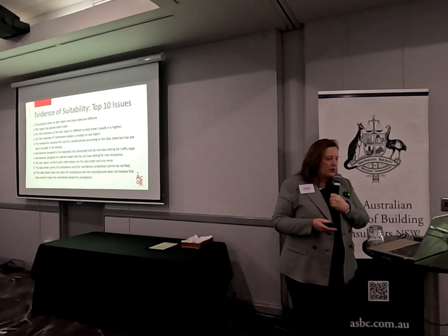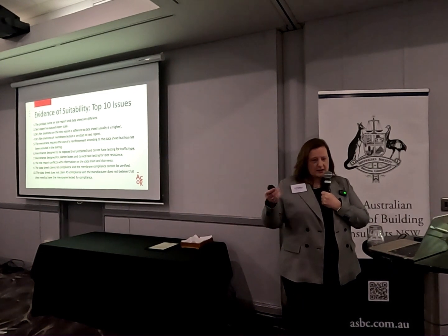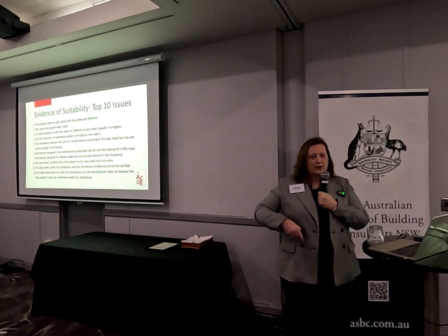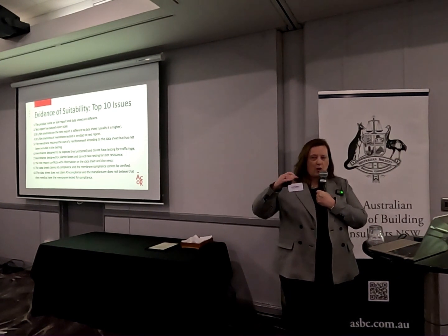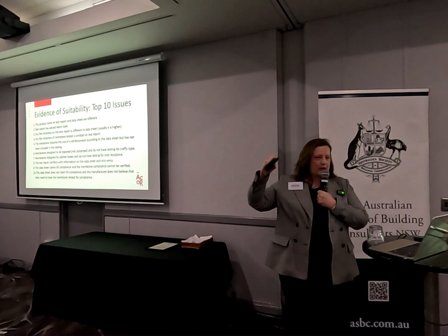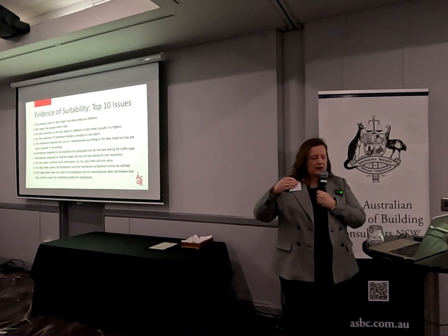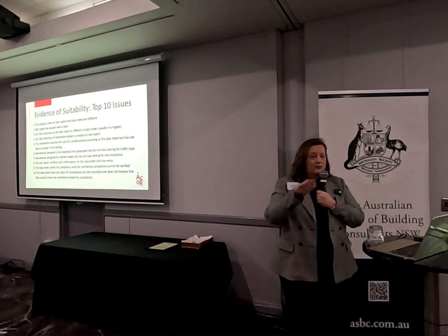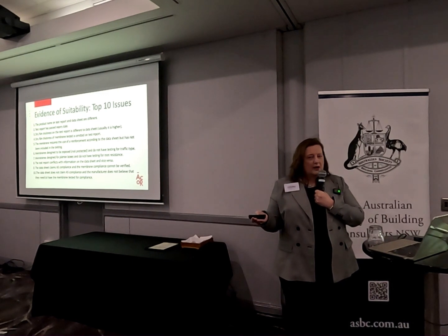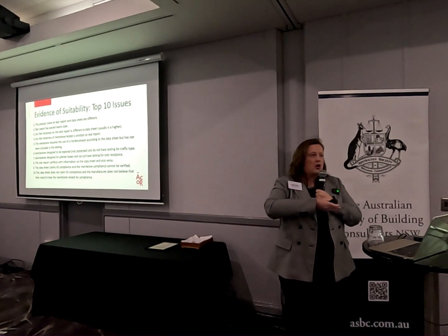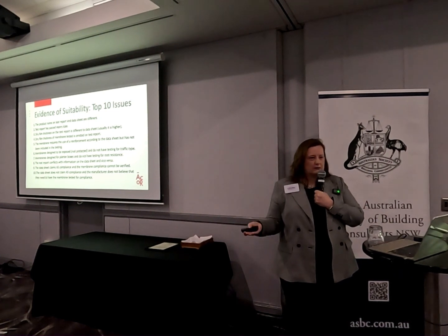And the same with the foot traffic, whether it's regular pedestrian traffic, whether it's vehicle traffic. There's an abrasion test in there which determines what membrane is suitable for which of those traffic types. And those tests are either not there, or there's a conflict between what the data sheet says and what the test report says. And sometimes the data sheet is claiming a higher level of traffic resistance than what the testing backs up.